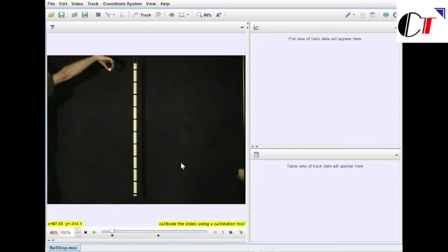And now after that, since the software will analyze the motion, the displacement, the velocity, everything based on the known measurement or dimension, you have to put the calibration stick there. In order to put that, you go to the calibration stick and then go to new and take the calibration stick there.